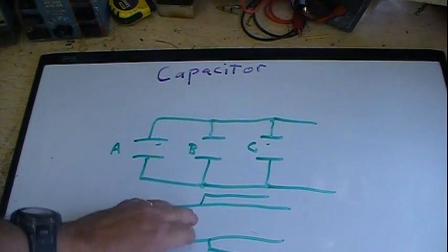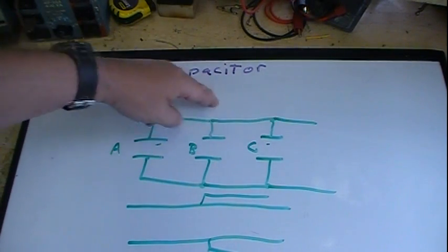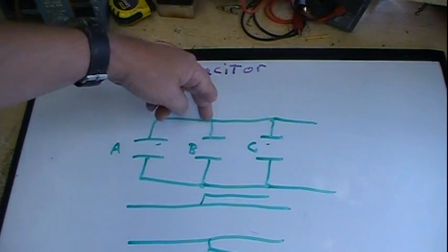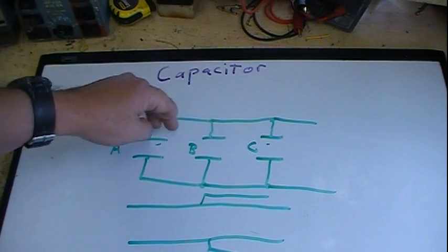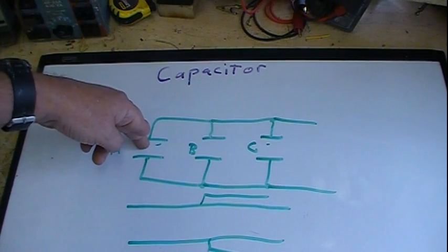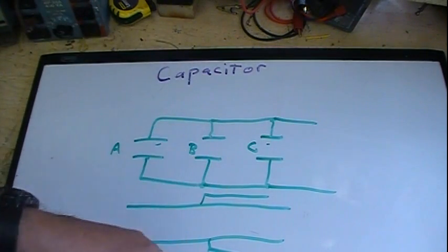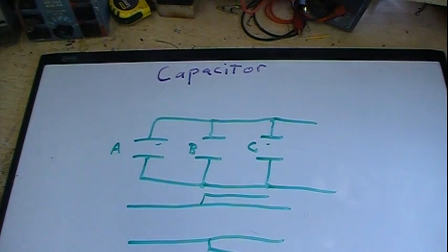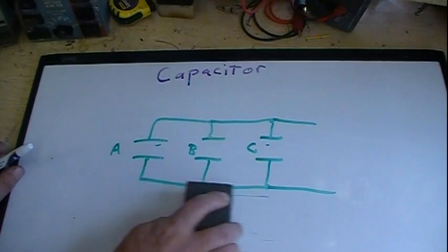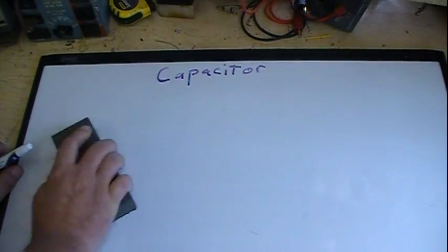It's the same thing. So that's why when you put them in parallel, the charge current comes down, splits off. As far as the charge is concerned, it sees these areas adding up to make one large effective cap. That is nice. Capacitors in parallel, you just add.